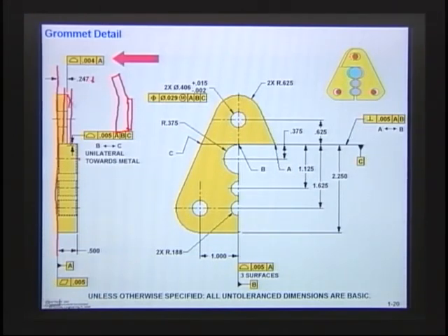So you see what profile does is it replaces the plus or minus. The good thing about profile is it establishes a datum. You come from the high points. With plus or minus, it's sometimes not clear. If the surfaces had a flatness on here, the minus would be checked in between the gap and a high point. So profile is very clear. Rest on the high points, come in and see where that surface is. So that's why I used a profile here. And you notice that I'm going to use profile on everything that we do here.